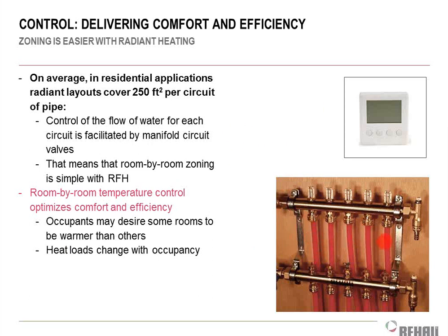All right, so on this one we've got 1, 2, 3, 4, 5 individual piping circuits, and let's say they're all 255 feet, right? We've got a supply header, we've got a return header coming back, and those headers are going over to my boiler plant. But this could all be controlled off of one zone, right to the left of this header where my little red dot is. I could have my zone valve or my zone pump, and that's basically turning on and off with the thermostat to allow water to flow through all 5 of these circuits at the same time. Or I could individually zone each of these 5 circuits if I wanted to, because of my application. So that's kind of the deal with that.